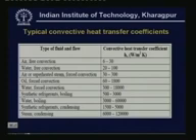For example, in the case of synthetic refrigerants, under boiling conditions the heat transfer coefficient varies anywhere between 500 to 3000 watt per meter square Kelvin. And if you have water, then you get really good heat transfer coefficients, again because water has excellent thermophysical properties compared to synthetic refrigerants. So, you can get heat transfer coefficients from 3000 to 60,000.